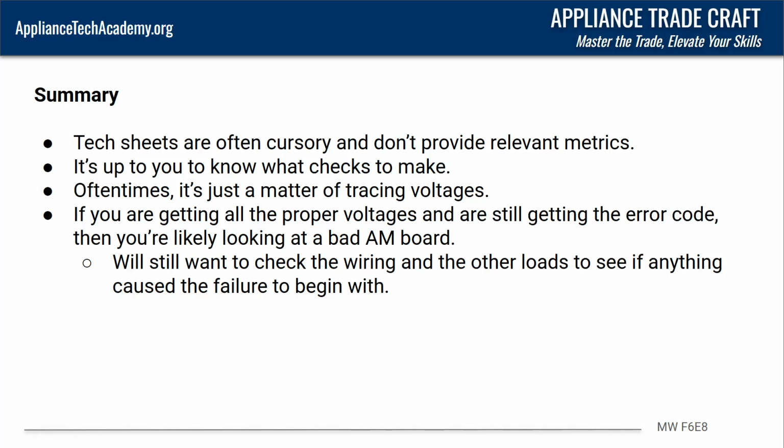Now, as an appliance technician, that's not the type of data that I want to see. Those aren't the testable metrics that I want to see. I want to be able to check my stuff, check voltages. I want to be able to check continuity, resistance, what have you, to determine where the issue is, not just check wire connections. If they're good, replace this board. I've seen so many techs do that, and that's why we're making these trainings, to go over common issues that you're going to see in the field.